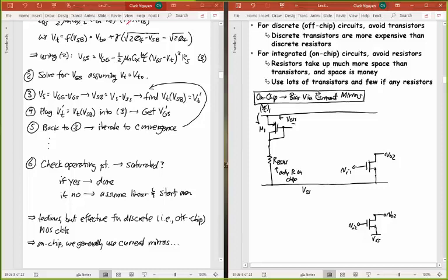Since it's PMOS, I usually make that absolute value. That's VSG of device 1. Okay, I'm dropping that voltage across this, according to my plus and minus that I'm showing there. And so across this resistor, I'm going to have a voltage there, and I have VSS there, which means that my current,